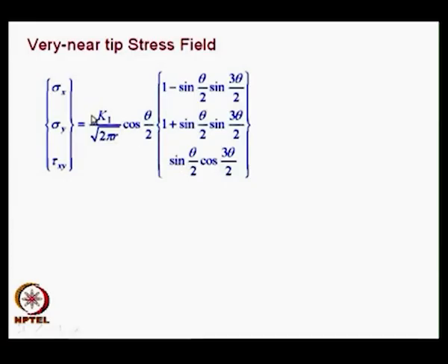I have what is known as the stress intensity factor, and there is a function of r and theta that is given. As the loading is changed, you would find the value of K1 changes. The value of K1 really determines the strength of the stress field. Suppose I have multiple loads which are giving you a mode 1 situation, then from the principle of superposition you can add the K1s for different types of loading.